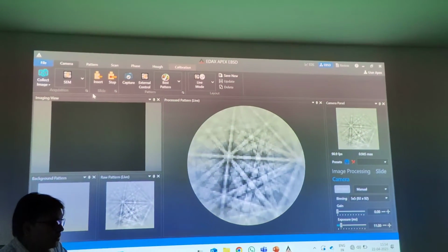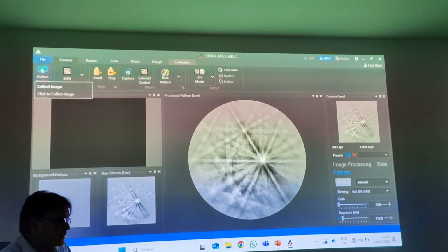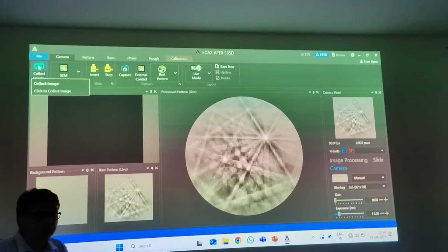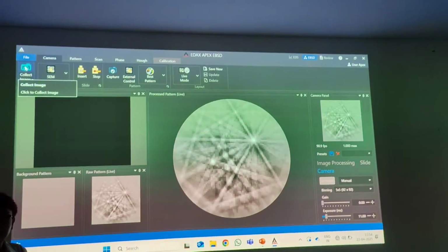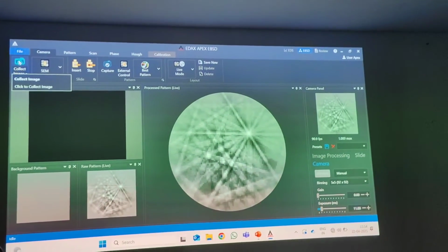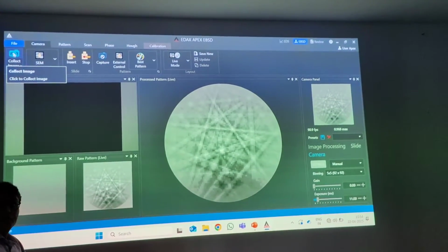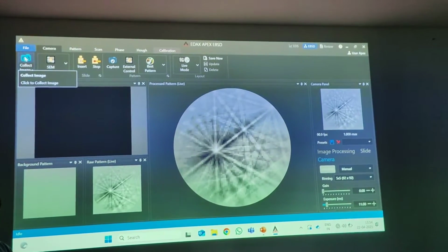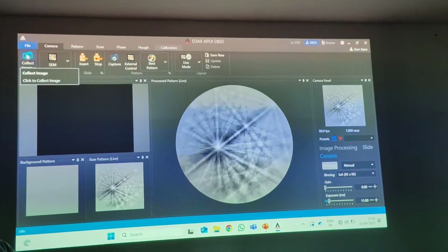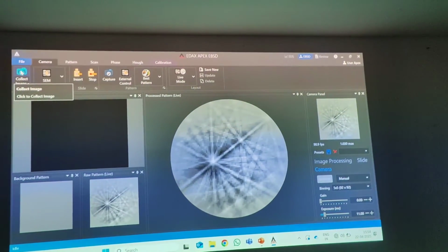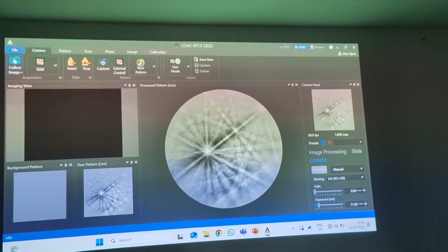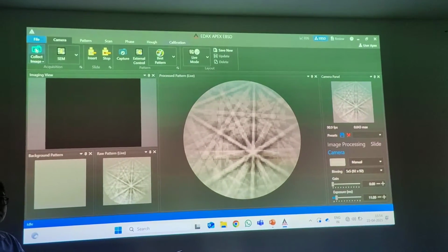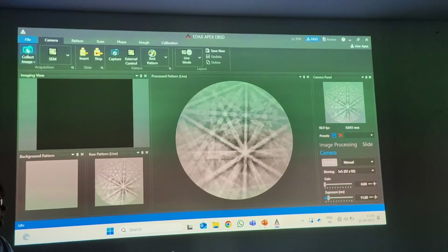So did he tell you what are the SEM conditions or what are the SEM parameters that need to be there for the EBSD part? CI value should be in between 0.5 to 0.9. That is for the EBSD part. But what should be the SEM parameters before doing any EBSD scans? So the working distance should be between 8 to 10 mm, and the EHT should be 20 kV. Yeah, typically we do that.